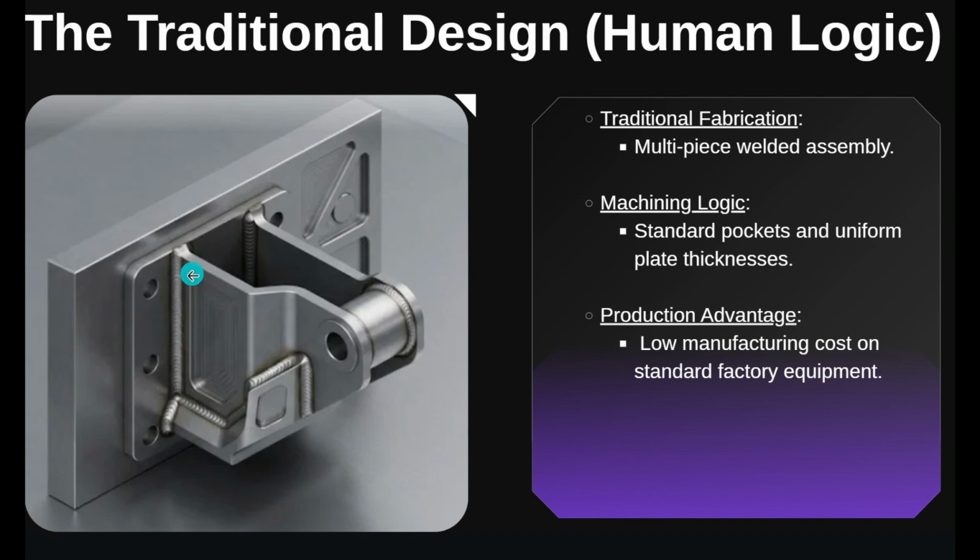On the factory floor, this design is excellent. It is incredibly cost effective to manufacture. Any standard fabrication shop can laser cut these plates and weld them together in minutes, or cut them from a single block on a basic 3-axis CNC mill.